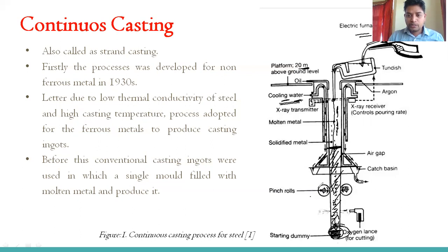So the pinch roll is applying compressive force on the product that we are getting, the solidifying material. By applying the compressive force, if there is any gap or any air particles, those are also released. And as I said, up to a specific height we have to maintain, because we cannot stop; the molten material will continuously come out.